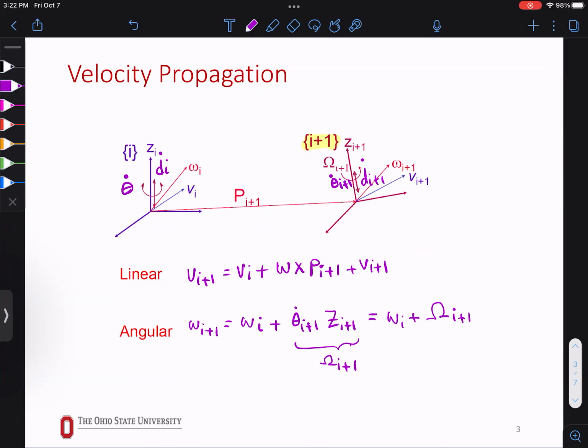Now, you asked, I'm using it with respect to that frame. What if I want it somewhere else? So we can use a rotation matrix. You will find this velocity with respect to, let's say, you start from the fixed frame, you're walking that way. So it was a good question why we're walking that way. Because once we have it with respect to this and we walk that way, if we wanted to change, we just use rotation matrices and then it converts. So we don't need to do extra work.